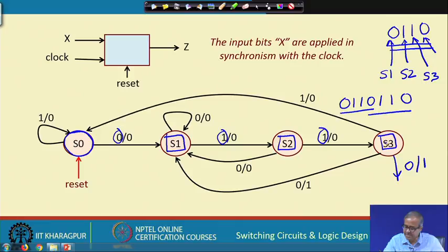Now, when you are in S3, what does that mean? You are at this point, you are in S3. Now, a 0 has come. This 0 is also S1 for the next pattern. So, instead of moving back to S0, we are actually moving back to S1, because you also need to check the next overlapping pattern, and it may start here also. So, you are actually in S1 for the next pattern.